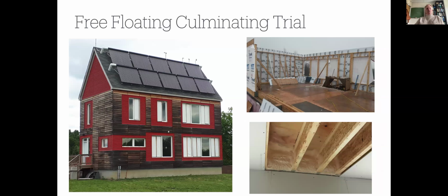All right, so most of these chapters are operating on these simple shoebox buildings, and we're varying one thing at a time. I think it's very important now to put all of that together to try and predict the performance of an actual building, which is obviously way more complex. We have now to face a lot of decisions about, do I spend my time defining the geometry, or do I spend my time trying to model air infiltration or predicting the solar reflectivity of the snow surrounding the building, et cetera, et cetera? Where do I place my efforts?